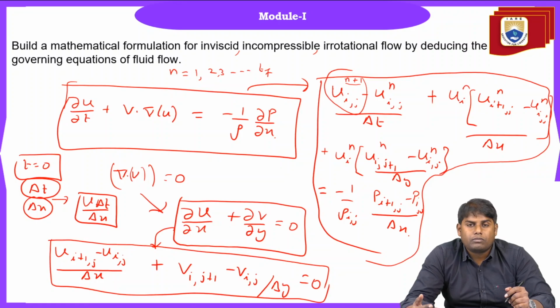If we have density, pressure, u velocity, v velocity, and w velocity as the five unknown variables, then when we consider the flow as incompressible, you have pressure, u velocity, v velocity, and w velocity, four variables, and four equations to solve very easily.